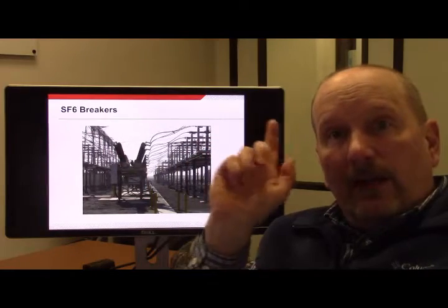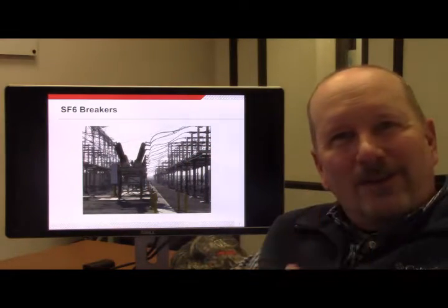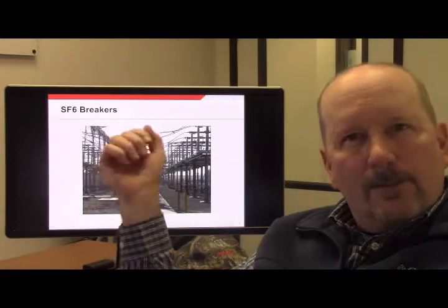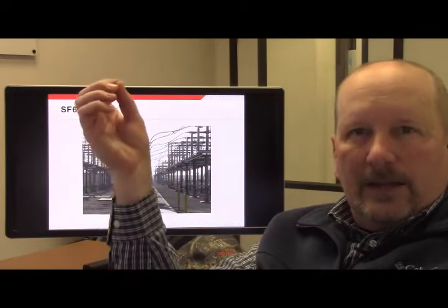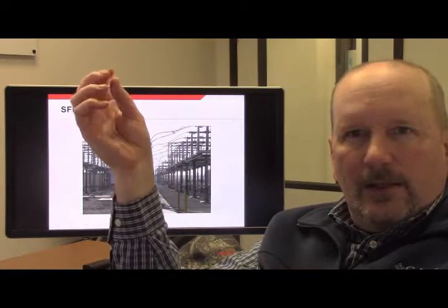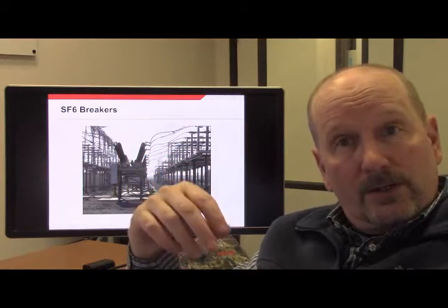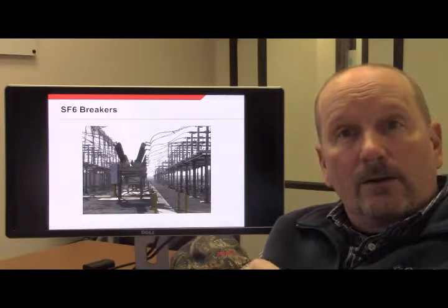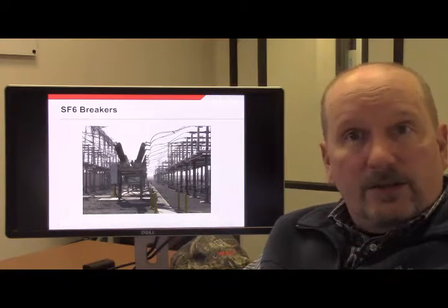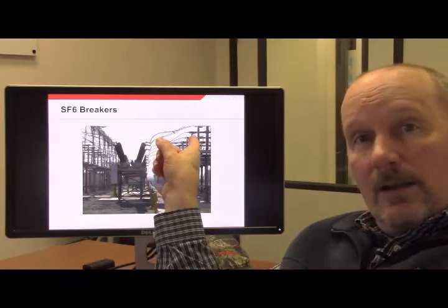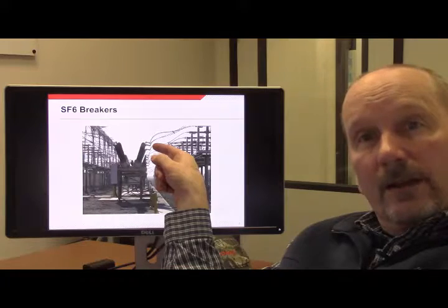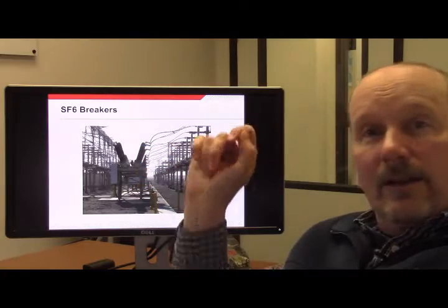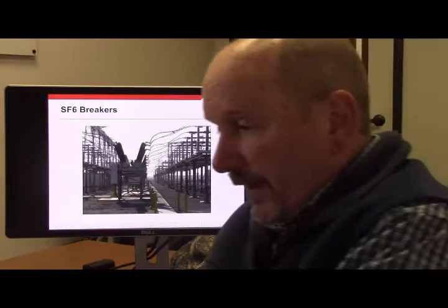Well, in Southern California, you've heard of acid rain. They actually have acid fog. Fog with a pH down around 2 or 3. And if they didn't do this, as you get condensation on the jumpers, it would drip down and get right onto the bushings, and then you'll have a little streak of conductive water during foggy nights, and it causes flashovers. So by doing that little fitting on the bushings, the little drips drop right off, and it keeps them out of having that problem.